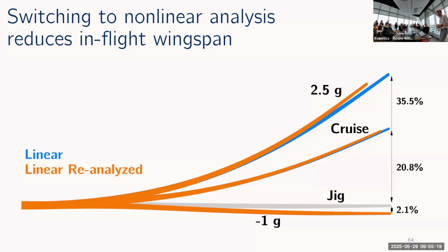But in terms of the fact that when I reanalyze this wing, there's very little change in, say, the cruise drag and the distribution of aerodynamic loads, for a wing of this high an aspect ratio, I think that's more generalizable. And also, this wing has an aspect ratio of like 19, which is well above what we're seeing probably even in the next generation of aircraft wings. So if anything, in real aircraft, this effect is going to be even smaller, likely.